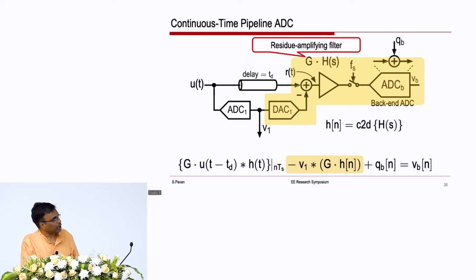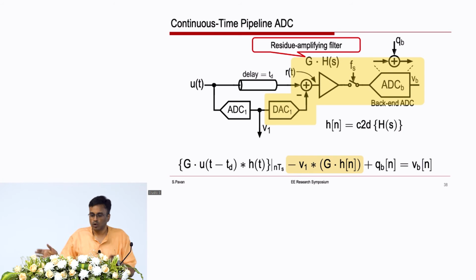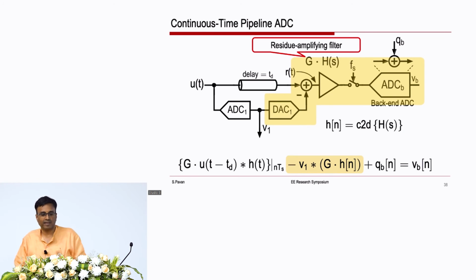And if you look at this yellow block here, you can see that this is a discrete time sequence. This is also a discrete time sequence. In the middle, you have a linear system, and therefore, you can always find a digital filter that relates the input sequence to the output sequence, right. So, those of you who have taken a DSP class, this is the same as what's called the impulse invariance transform, if that rings a bell.